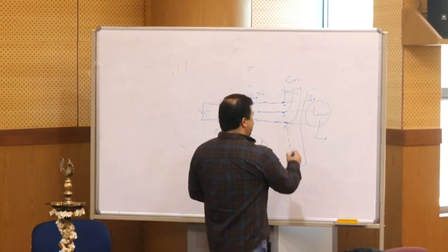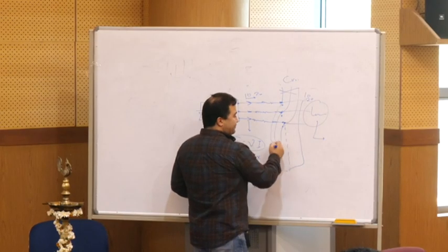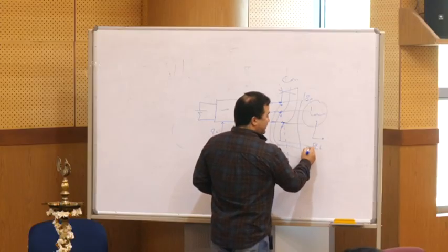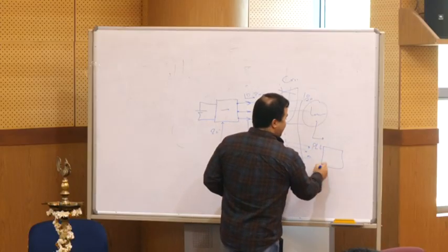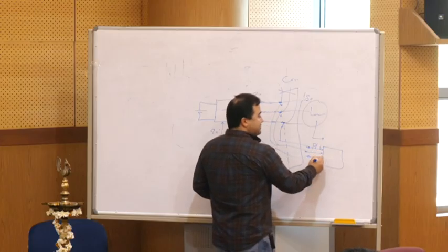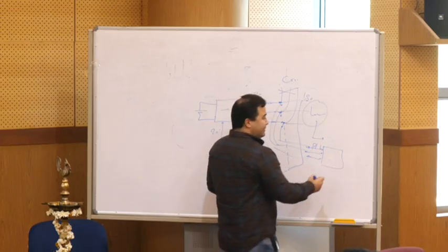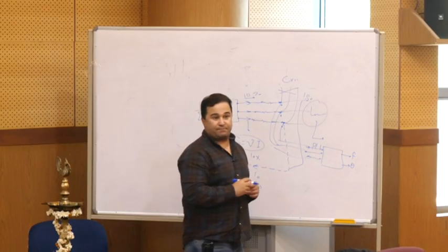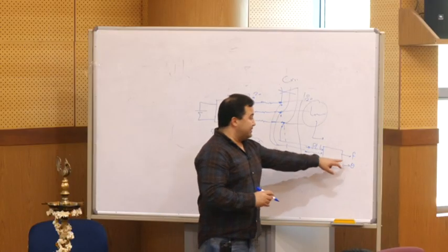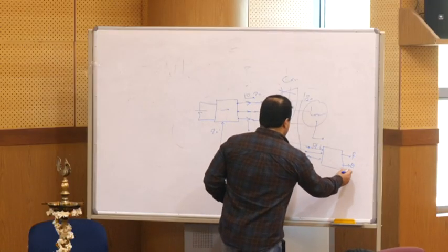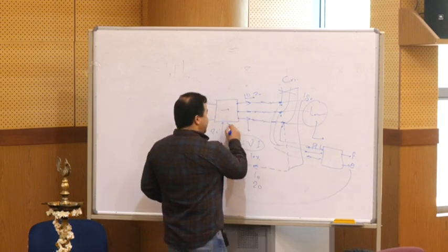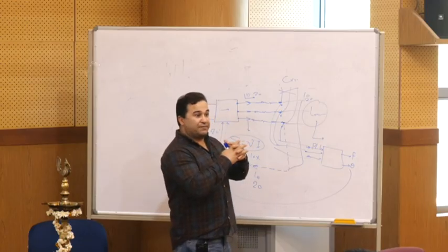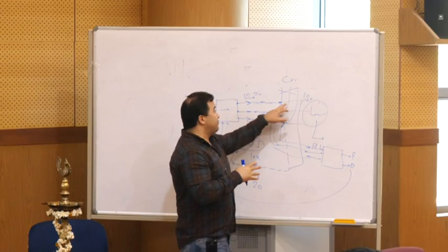So the phase lock loop is like this. I use the PLL, and in the PLL we have the voltage of 3 phase. Then the output will be frequency and theta. By this, I can control my converter and tell it that when you synchronize, it should be in phase with the grid.